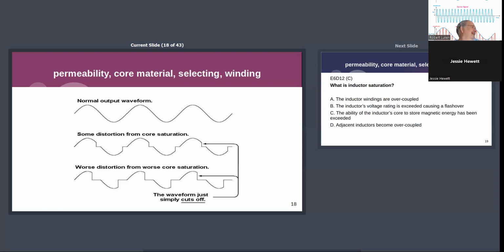The SWR was like 1.2 to 1, and then you watch your SWR go whoop. That's what's happening. You just put too much energy into the little core. If you do it again, use 2 cores. It'll last twice as long.